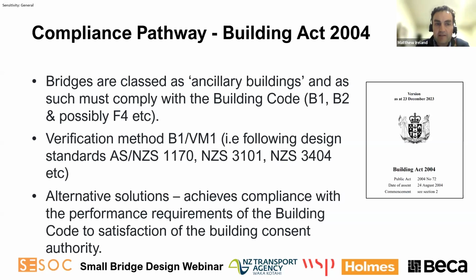So compliance with the Building Act. Bridges are classified as ancillary buildings to the Building Act, and therefore must comply with the building code. So there's B1 structure, B2 durability, and also possibly F4 for falling from heights, and potentially some others depending on your structure. As was alluded to earlier, there are three possible ways to achieve compliance.